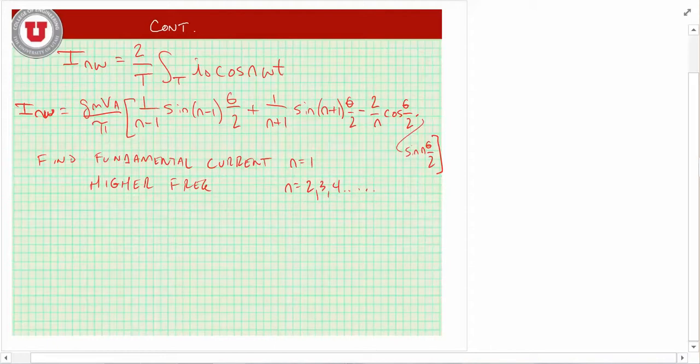Okay, so the reason that we showed this amplifier as having a tank circuit is that the filtering at the output removes harmonic distortion, so that the only power delivered to the load is at the fundamental frequency. Of course, the filter that we would need, we would have to have a very high quality factor to realize this.